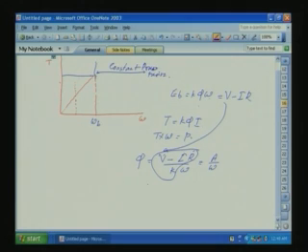So what is torque? Torque is equal to K into A by omega into I, and K is constant, A is constant, I is also constant. We have reached the maximum level. So this can be written as T is equal to some constant K2 by omega. This shows T omega is equal to constant. This is called constant horsepower. So whenever we are changing the flux with respect to speed, we are in the constant horsepower region.